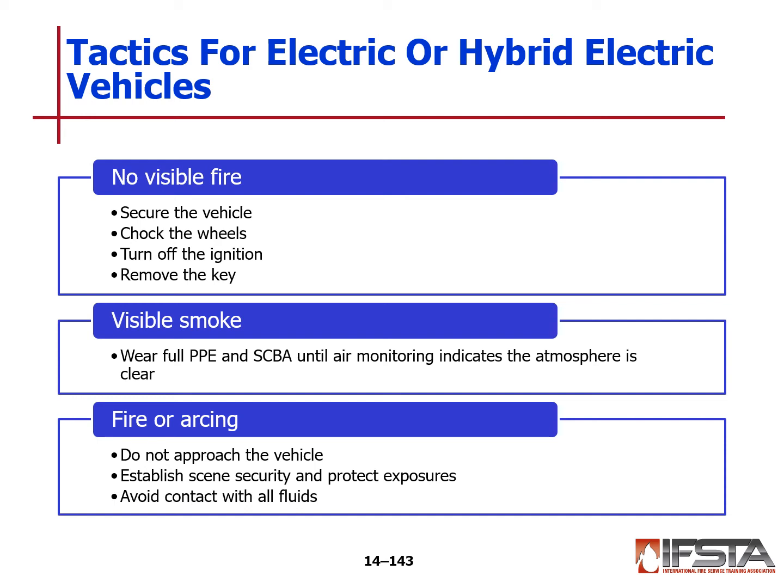When we have visible smoke, full PPE, SCBA breathing air is required until the air monitoring indicates that the atmosphere is clear. With any fire or arcing, be careful and do not approach the vehicle. Establish your scene security and protect any exposures. Avoid contact with all fluids.